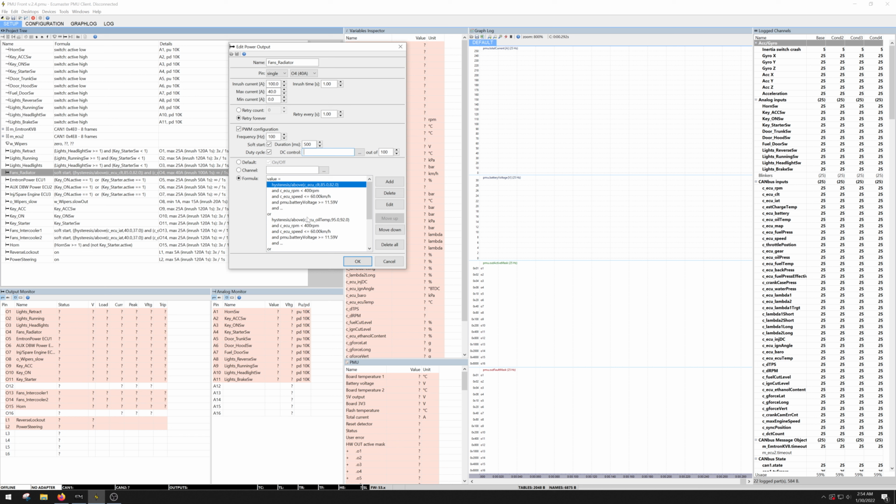Or if my oil temp, since I have my 2 oil coolers on top of my radiator, that fan also pulls from there, right? So if my oil temp goes over, the fan kicks on. Or if my coolant temp goes over, this overrides everything. Doesn't matter what the vehicle speed is or the voltage. I'm sorry, vehicle speed or the engine RPM. So this means if the vehicle is parked, it'll kick it on. And same goes with oil temp. If the vehicle is parked with the engine off, it'll still kick on.